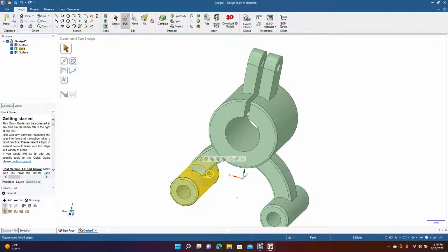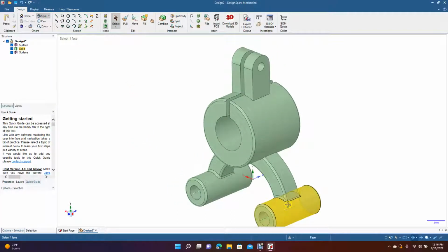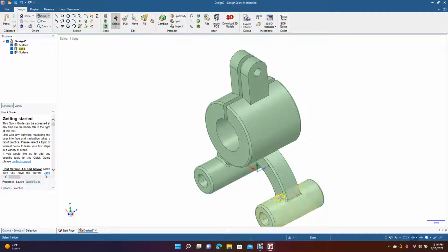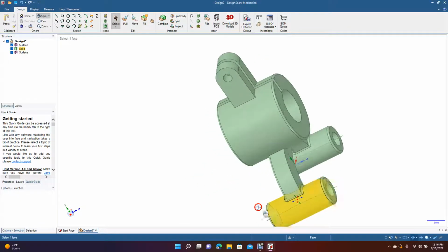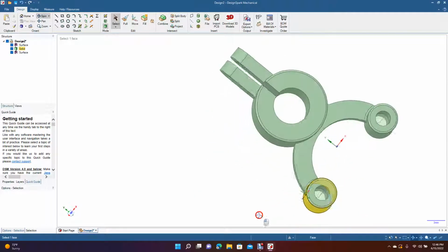See how it's selected? And then you want to type 0.3. Okay, this got on the other side, which is what we wanted. So you want to do the same right there. Click till you got that whole square selected. Then you want to type 0.3. Okay. And this right here, when you know that there's a fillet in there, it makes it harder for this to snap right here. So this would be less likely to snap.